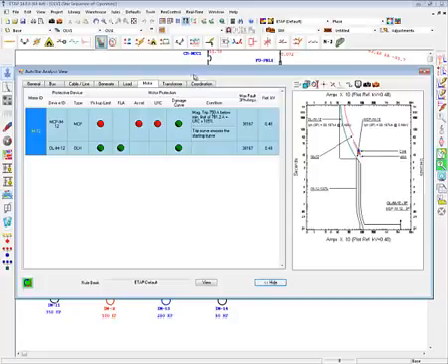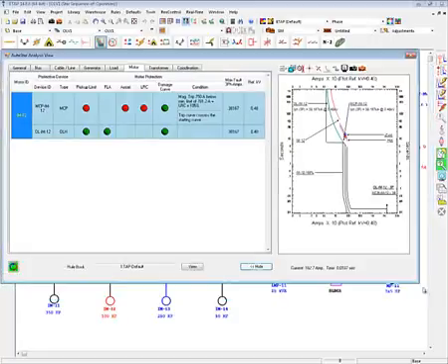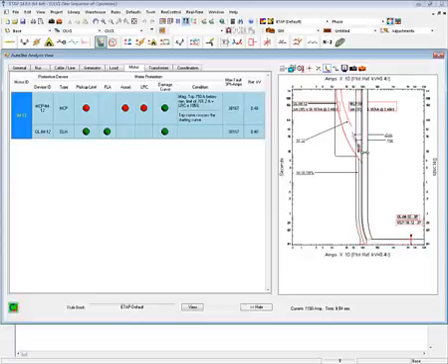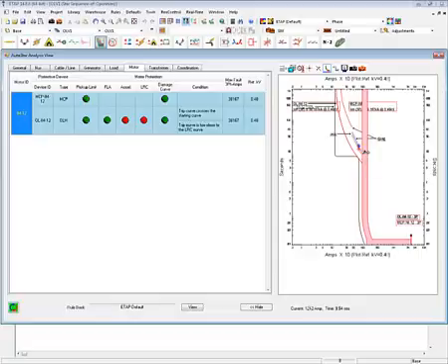So instead of taking an engineering decision for motor protection, the software analyzes your system and tells you points of concern, or points which are not correctly protected or coordinated, by way of a visual display. Similar to our regular star view, we're going to set up the protection scheme. We're going to adjust this MCP in a manner that it recalculates the effect of the MCP on the system.